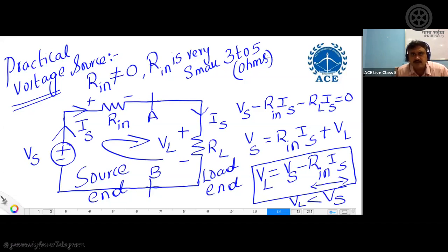So initially when you test it, it will be 5 volts. It will not show 4.9599. It will show like that. But after 6 months, if you see, it will show somewhere around 3.5. So where is that 1 volt gone? You did not connect any load. Suppose if you have used it in some watches or some TV remote or any AC remote, the voltage will automatically reduce. But without using, how has that voltage come down? That is because of this internal resistance only.